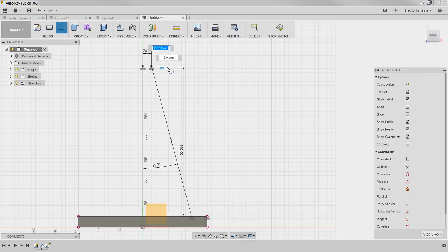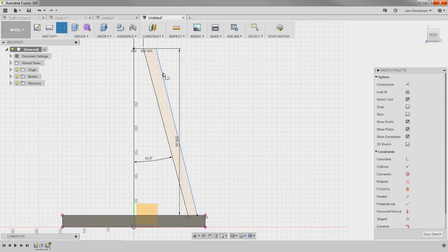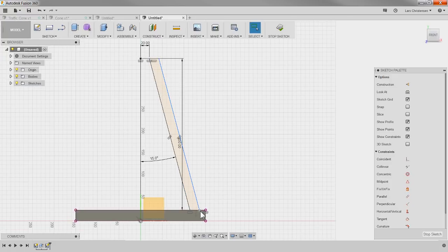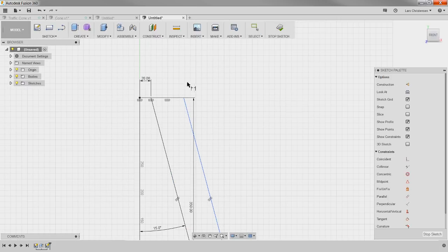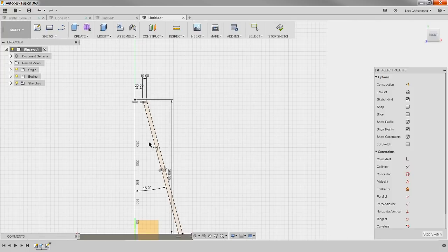I'm going to drag a line out. This one I'm going to make sure goes horizontal. Drag it down, make sure it snaps into space down here. Again, it's blue, so we've got to work with it. I like the parallel constraint, so make these two lines parallel. And again, if you're unsure what you're missing, then D for dimension, we can dimension that one, that was 10. Now we're exactly back to where I was before when I revolved. Hopefully this was not too fast.